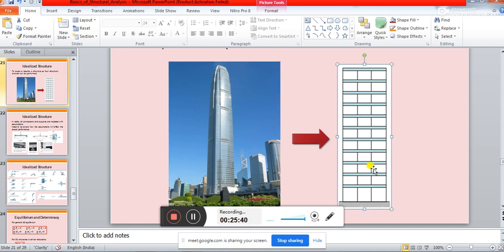We make multiple two-dimensional frames, and then we are idealizing this big structure as two-dimensional by making simpler frame structures, and then finally adding up those frame structures, analyzing and putting some conditions on those to get the final value of bending moment, shear force, reaction, whatever it may be.